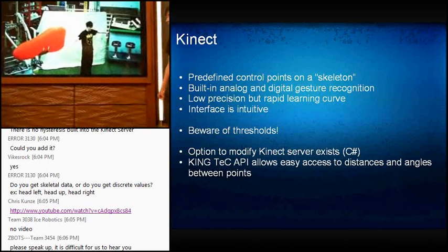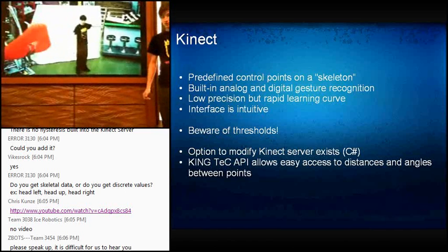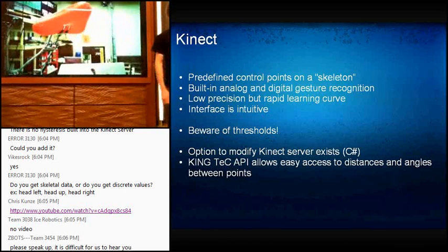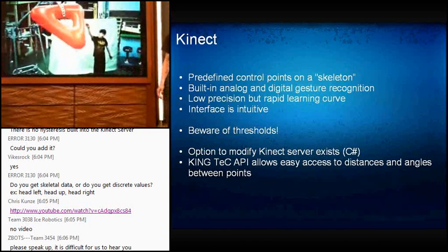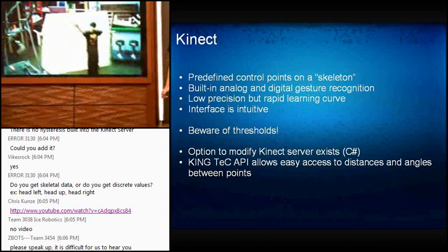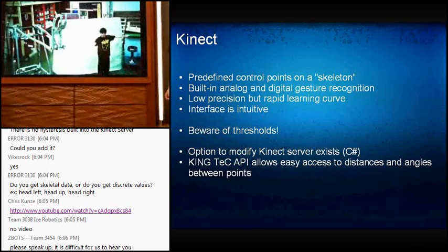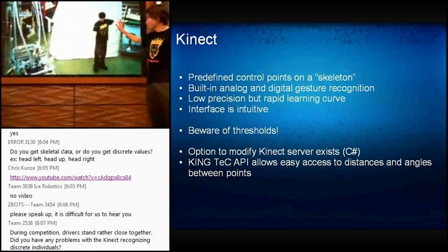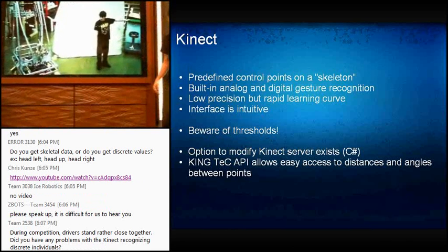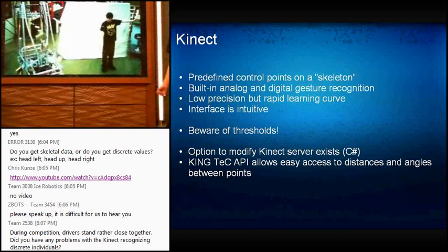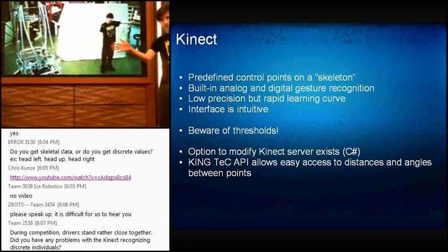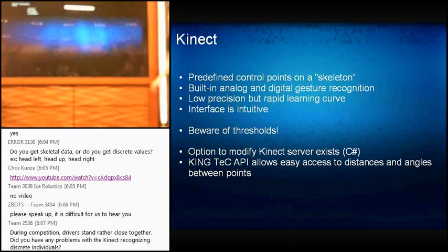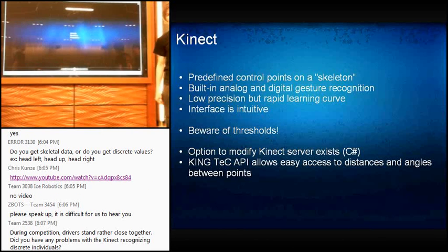And one thing that you saw there is that you want to make sure that you remain perpendicular to the Kinect, otherwise it starts to return null values, and if you're using that to control something, that gets a little irritating. You also want to make sure that, if possible, you have a flat screen or a different flat object behind you, because if you are in front of some really curved surface or with a lot of weird indents in it, it's just going to give you a ton of weird values, and you're not going to get very good success.